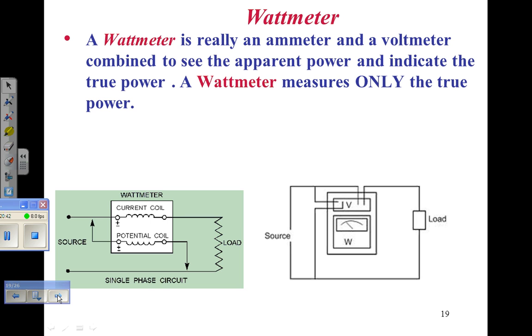So if we put this wattmeter on that 120 volts that's pulling 10 amps for that motor, the voltage portion of the meter will be connected to the circuit in parallel to read the voltage and in series to read the current, right? So all that 10 amps is going to go through the wattmeter. So it's got to be a 10 amp or more rated wattmeter, or 1200 VAs or higher rated. So it's got to be a pretty good one.